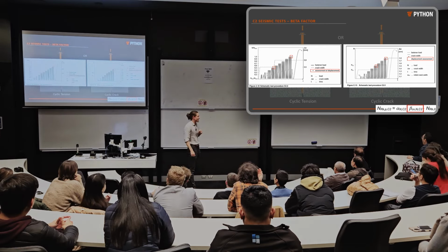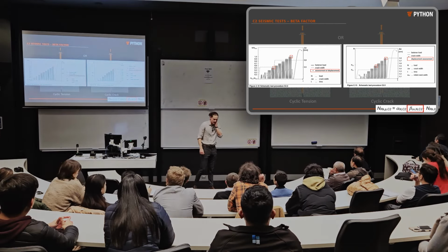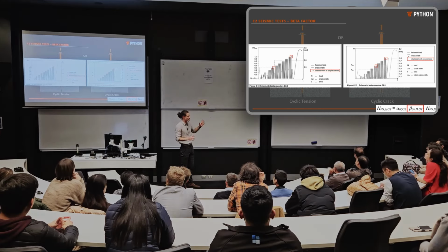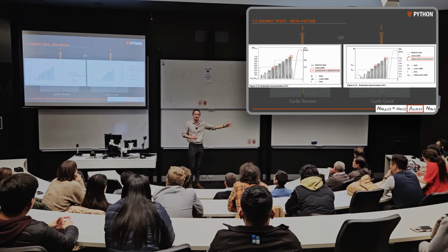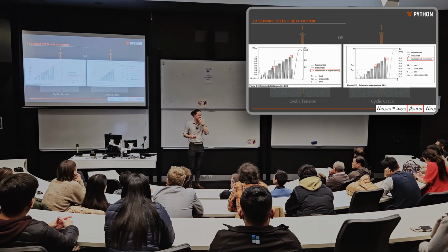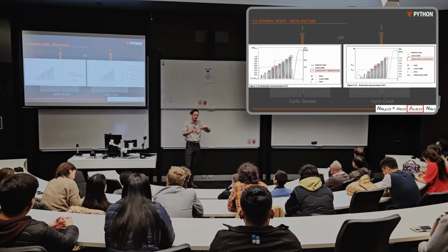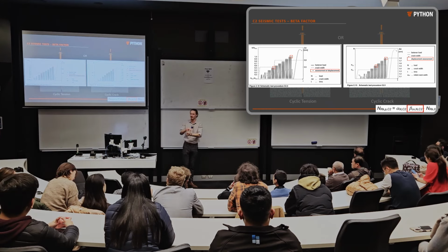Now, quickly on the beta factor. A simplistic version would be to think about displacement. Your alpha factor is looking at loss of load carrying capacity for the scenarios we've talked about, and your beta factor is looking at displacement performance. You measure it at 2 points in all your tests, at the 0.5 crack width and at the 0.8 crack width. Again, you'll be sick of me saying this, the 0.5 crack width being service level conditions, the 0.8 crack width being heavy seismic loading.